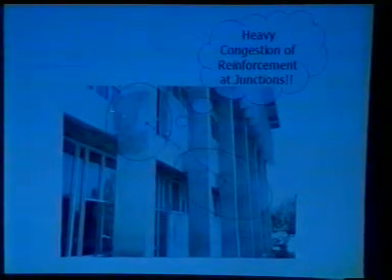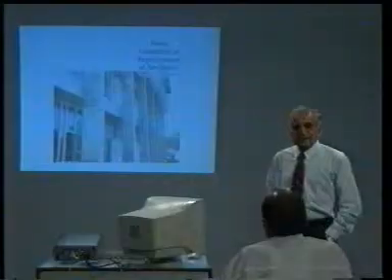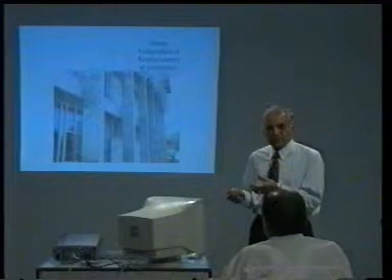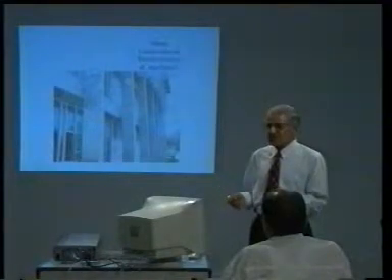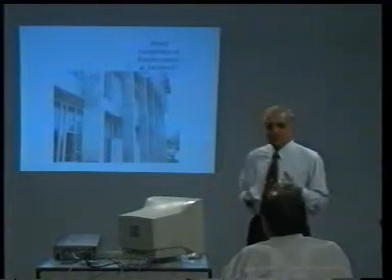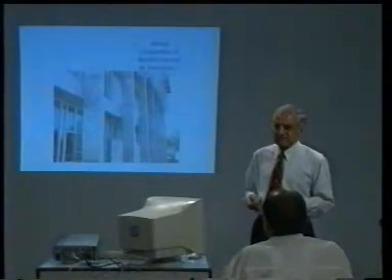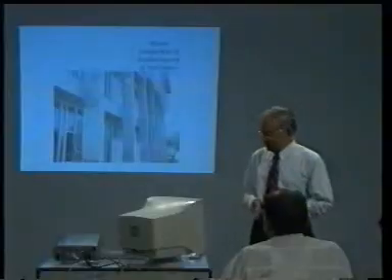If it was poor workmanship, it would be only here, but this is the thing that you observe on all these column beam junctions. So, this is the result of heavy congestion of reinforcement. This can be avoided by providing large diameter bars, a lesser number of bars, grouping the bars, and also providing highly flowing concrete by using proper plasticizers and a good slump.